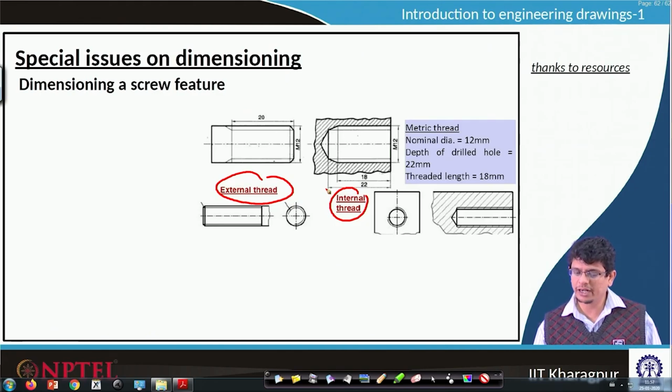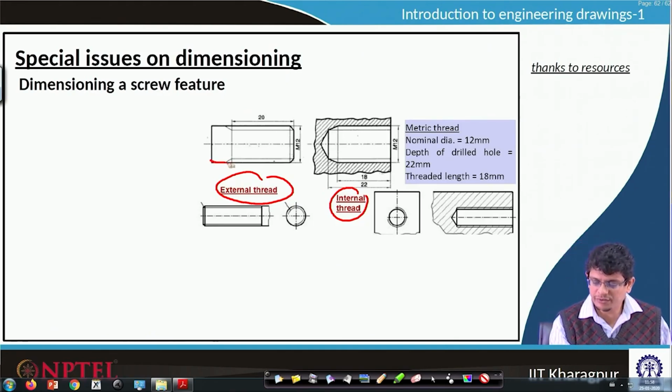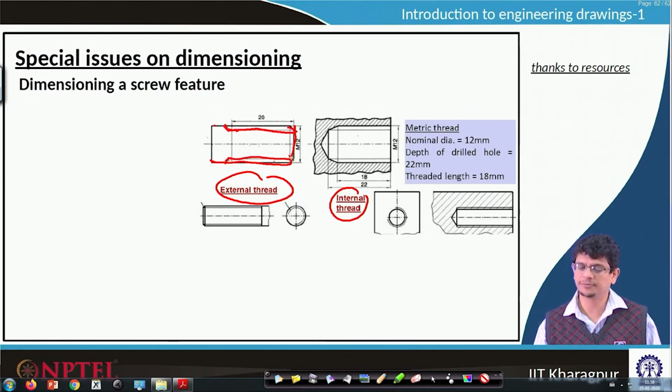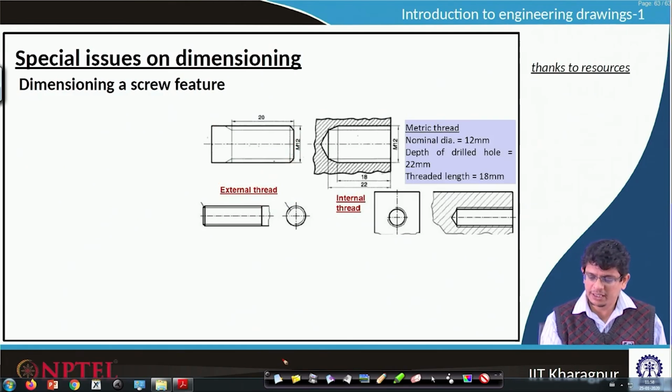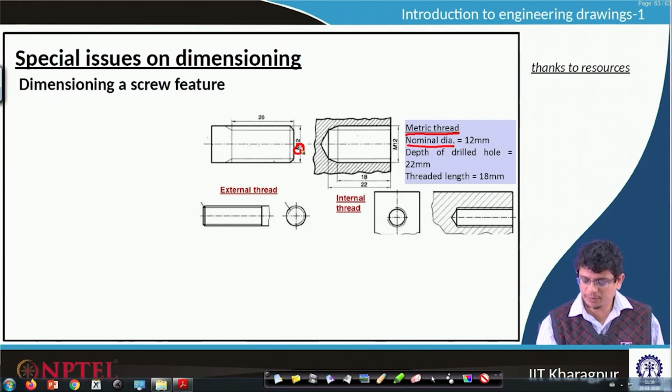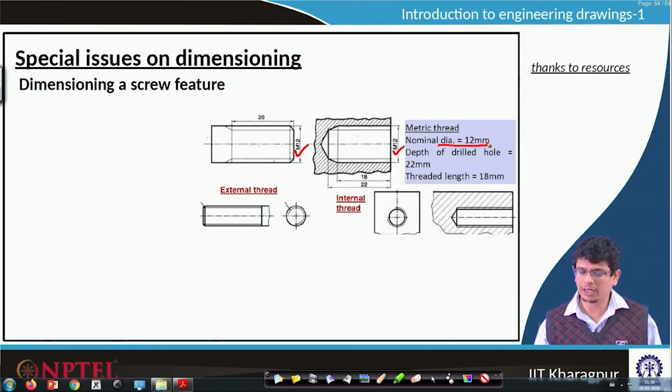More details we will learn in future classes. But whenever we see rectangular portions, tapered ones and slightly curved lines, it indicates that we are dealing with threads. Usually these threads are shown by the metric M designation. For metric threads there is the symbol M. Perhaps it might have a diameter of 12 mm.